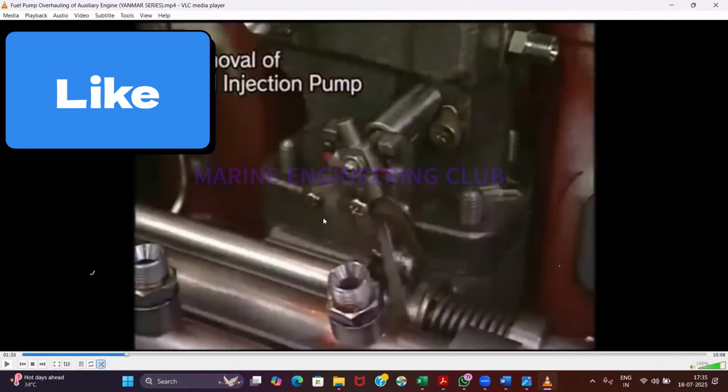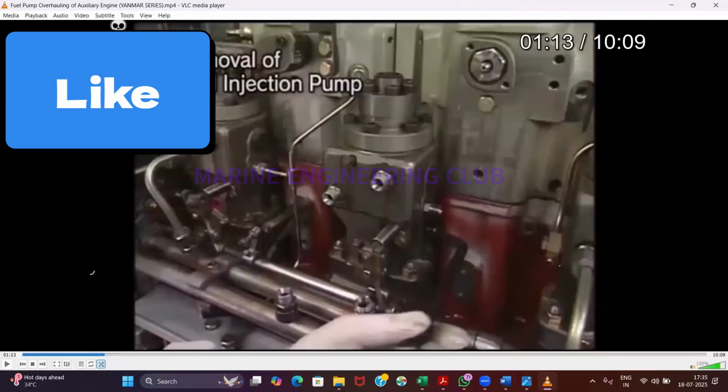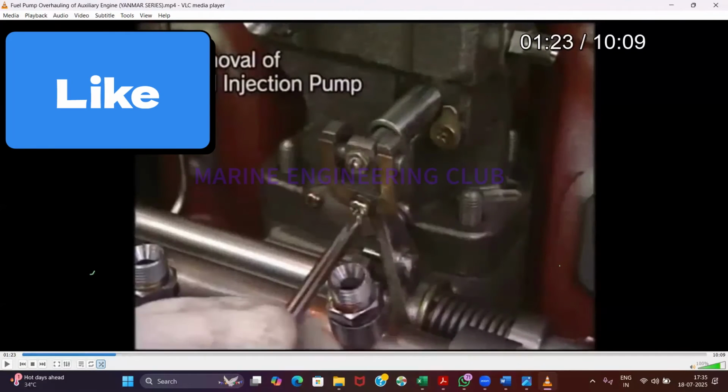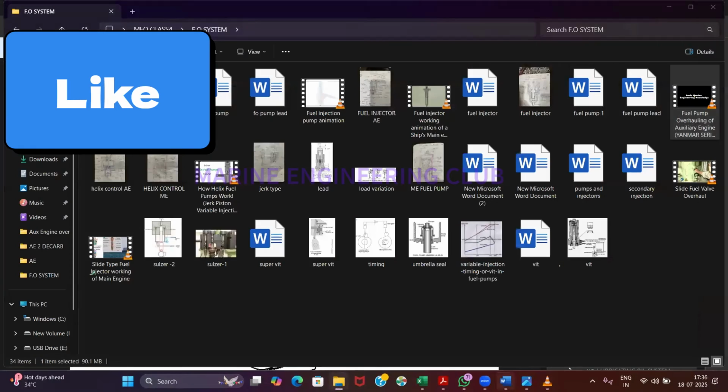Okay, here you can see this screw. So these two screws will remove this plate. Okay, the plate comes off from behind, and then you can see through and through this marking. Can you see it? There is a plate over here and 2 screws over here. You have to remove these 2 screws, then you will be able to see this marking. Okay, but this is not in every generator.